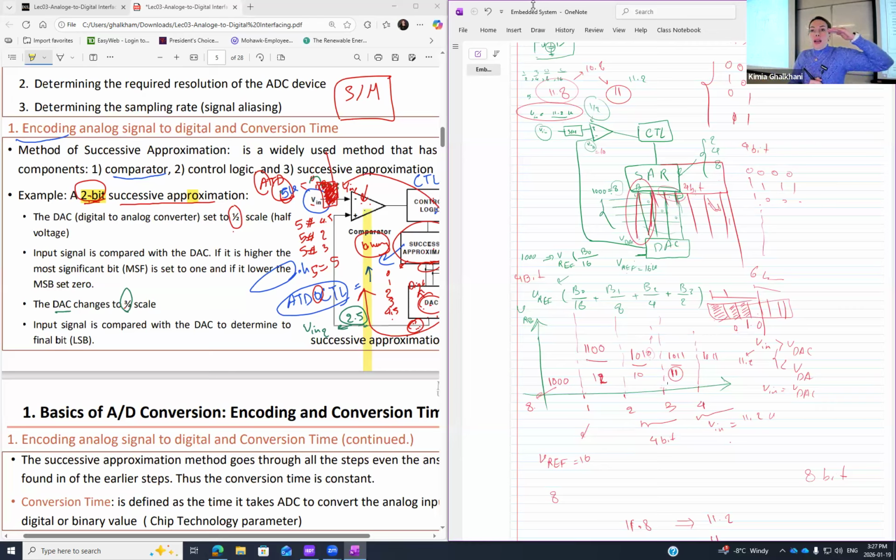This one always will stay as it is. So on my comparator, I have 2 legs. One of them is constantly my input, and I'm going to explain right now why I have to keep it constant. The reason is exactly this picture. My time of conversion for each step must be the same.